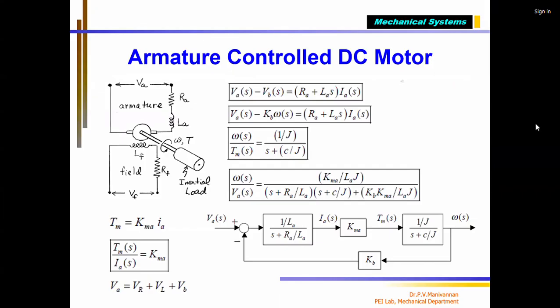Fine. Okay. Now the back EMF is developed only if I try to vary this armature control. So the equation is written here, and it is fully expanded. VB is expanded as KB into omega, but it has the opposite sign of the applied voltage. That's why the net voltage is the difference from the applied voltage. According to that, this is the equation.